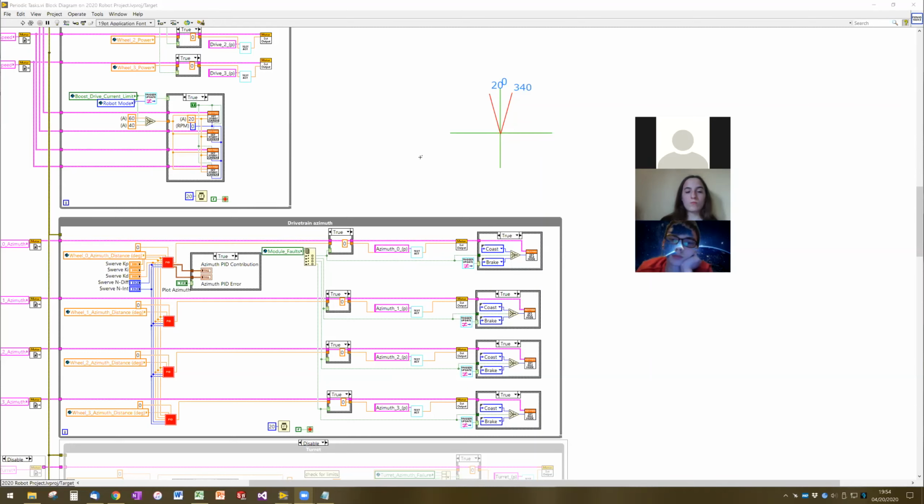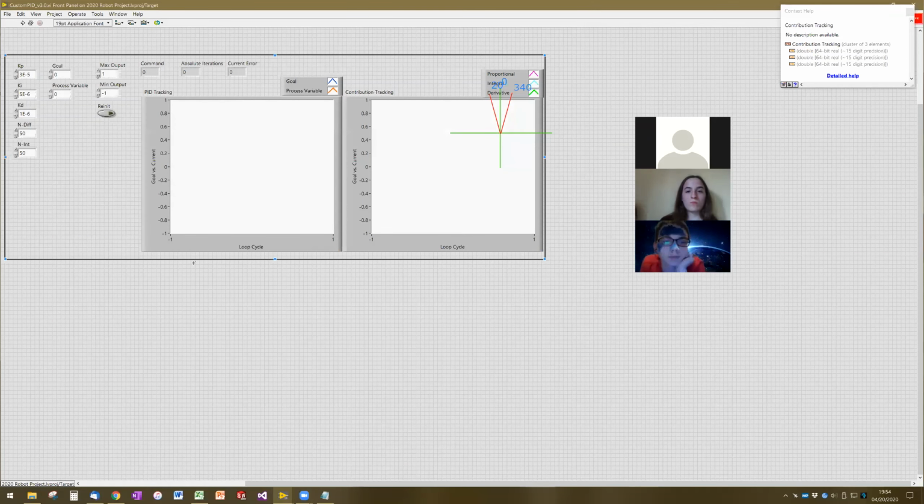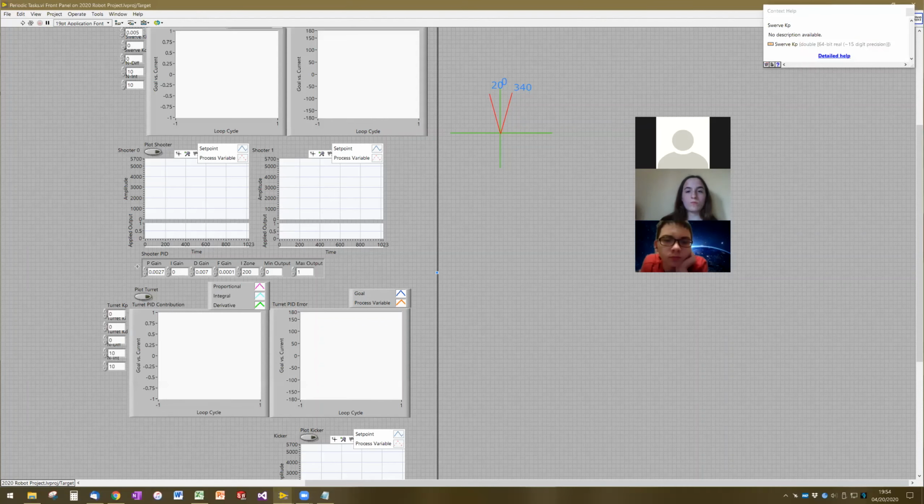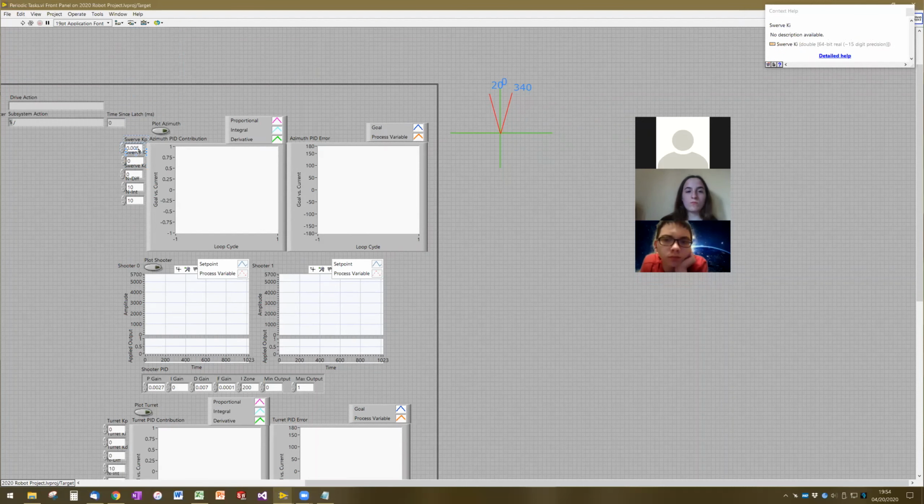Okay. And then the last question we have on the PID is, if we look at the values here, you'll see that we have a KP of 0.005, and then we have zeros for KI and KD. Can anyone remember why for the Swerve drive we aren't using either the integral or the derivative term? That's because we have a lot of internal friction, so it does kind of act as the derivative, and we don't need to code that in.